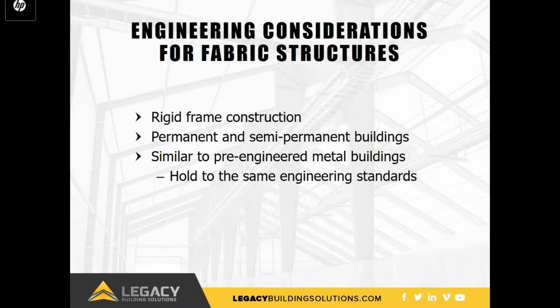In a metal building, steel sheets are screwed to light gauge subframing that is attached to the building frame, creating an exoskeleton that structurally aids the frames. In a fabric structure, the fabric is attached to the frame via a keder rail. The fabric is not calculated as an exoskeleton for the structure. This support is added to the structure using secondary framing members and cables or cross rods attached to the frame itself.